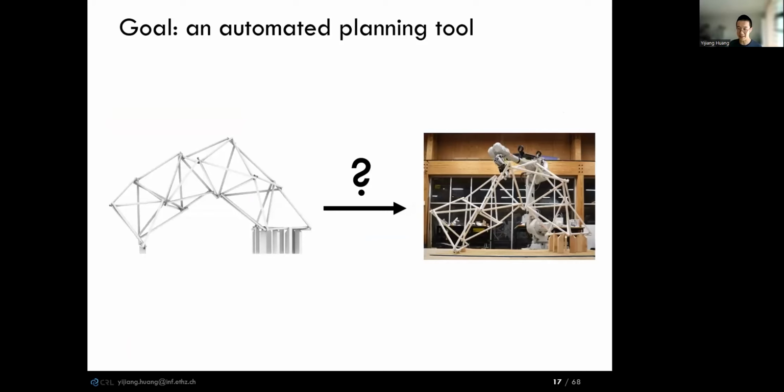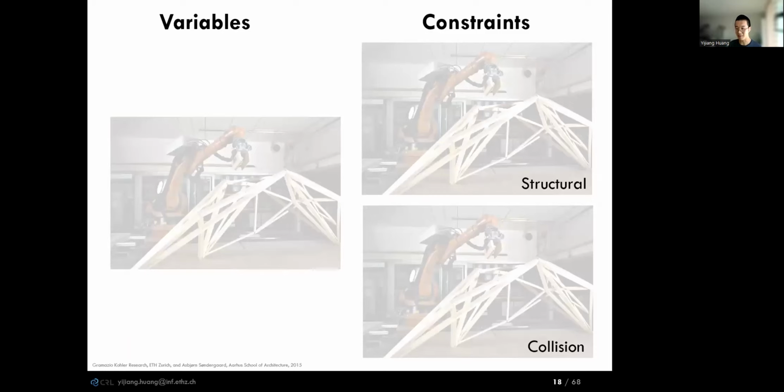The first project investigates how to automatically program a robot to assemble arbitrary bar structures. So we want to generate the equivalent of a slicing algorithm that you would use in FDM printing, to allow for more flexible robotic assembly of non-standard elements. But the planning problem here is much harder than just programming a gantry machine like a 3D printer. The spatial assembly requires us to think carefully about the assembly sequence.